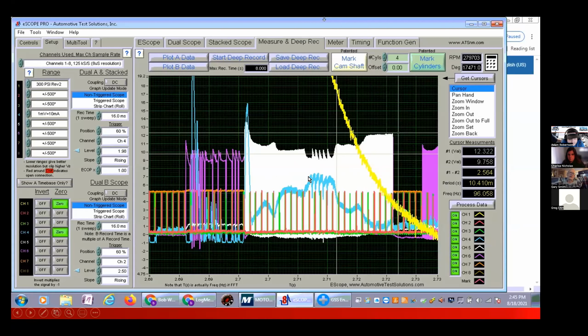When an overcurrent or under voltage occurs, and in this case it's going to look at that as both, because it's going under voltage here and it's going overcurrent here at the same time, this motor driver is immediately shutting off.